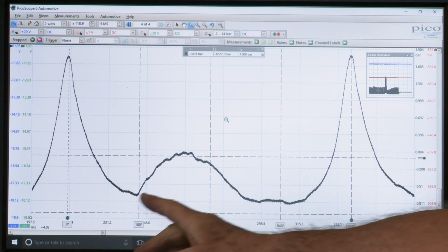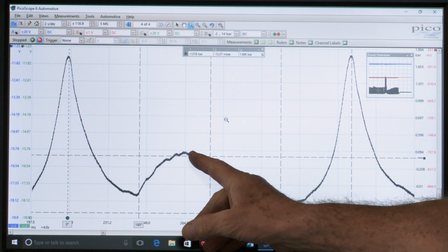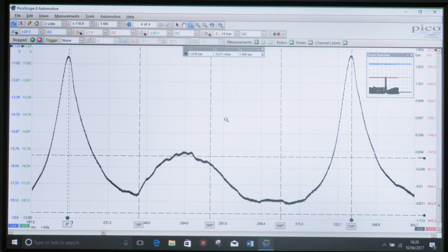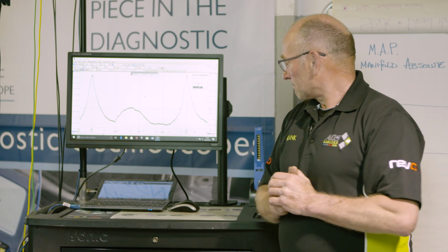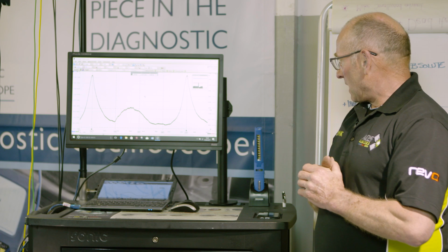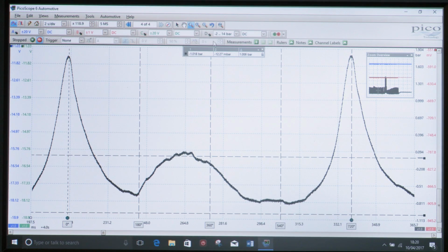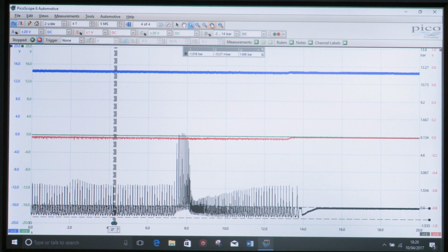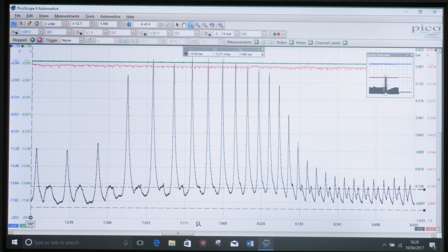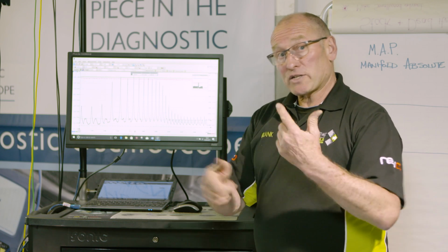So very much what happens here and down here is now very much part of the computer control of the intake valve timing. So that's my take. Also, you may wish to look at peak pressures, of course, and acceleration. We did accelerate the vehicle, and you can see under acceleration, the compression has gone to just short of 7 bar, which was the same as it was at low engine speed cranking.